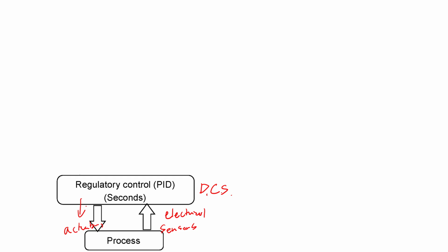One thing about a distributed control system, particularly when you're working with what are called single input, single output controllers, is that each controller is kind of just doing its own thing. It's not aware. It just reads in the one sensor and spits out the signal for just one actuator. So it's a one-to-one mapping. If you're trying to control temperature by changing the process heat, that's all that controller knows. It doesn't know anything about changing feed flows, for example, which can impact temperature, but it won't be able to incorporate those.